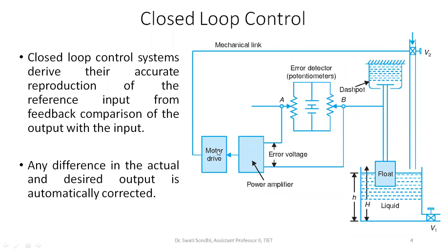Okay, so of course the speed of motor is proportional to the voltage that you give to the motor. So this, I don't know whether you have studied this concept or not, but in the lab we are going to have one experiment in which you will study the relation between the voltage, the current, and the speed of the motor, even the position of the motor. Okay, now this motor drive, motor depends upon type of application. It can be a simple servo motor, it can be a stepper motor, that depends upon what kind of application